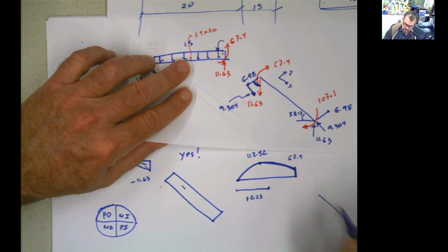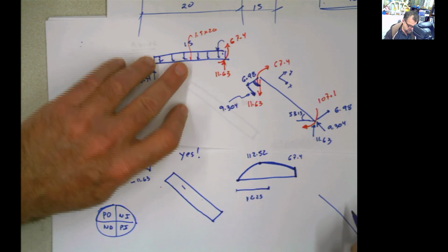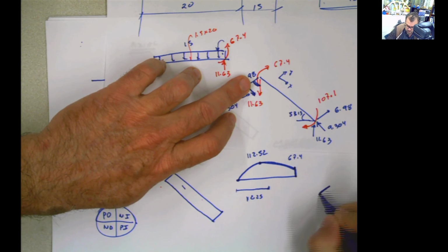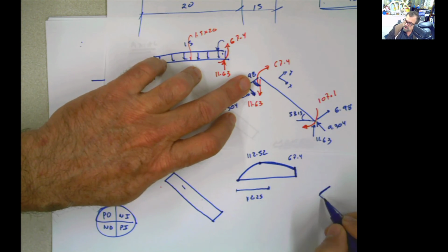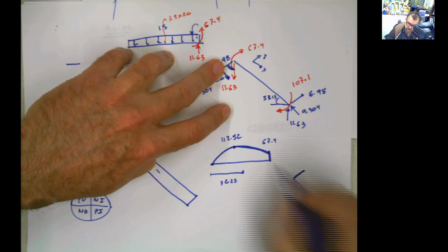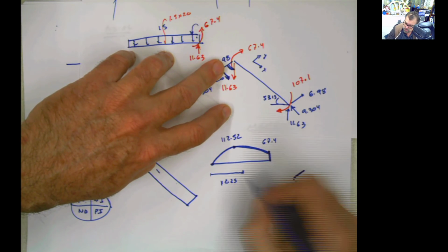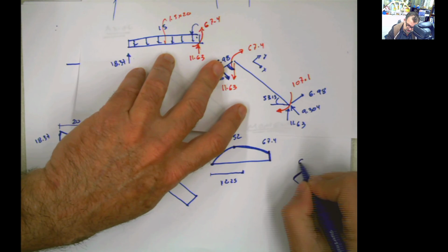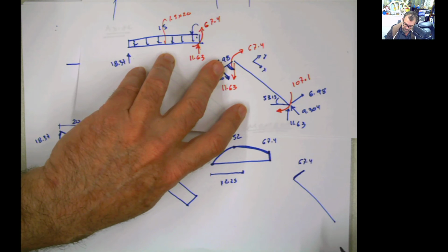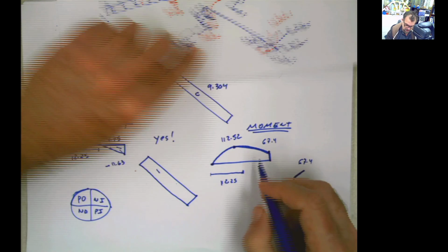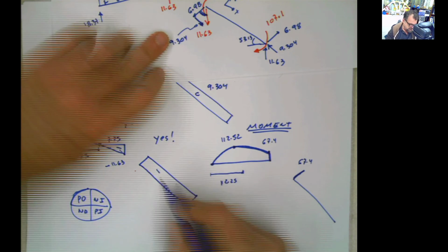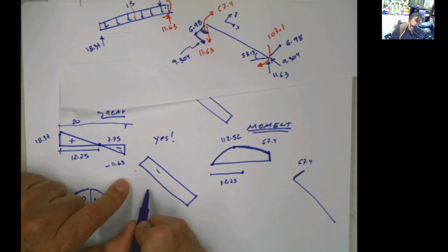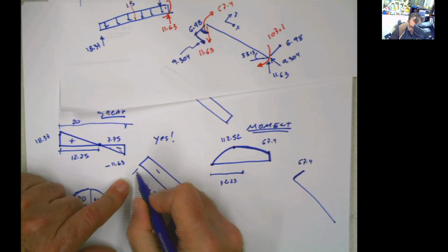Yes. Now we go to this other part, and in this other part, as you can see, we start with a push up, 67.4. It has to be the same one, except that you have the third leg. If you have a third or a fourth leg, then the summation of all of them is what is going to change things. So this is 67.4 right there. And now I have this negative diagram here for shear, and this is 25, remember, the total distance.